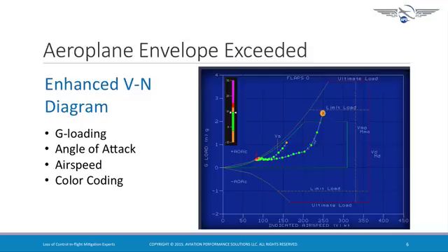So the goal in this particular case is for the airplane to ideally stay within the envelope where all the factors are going to be green. Okay, in this particular case, we can see as the airplane unloads, as he gets slow enough, though, his unload isn't quite sufficient for the airspeed encountered to avoid the stall, which is what the red indications are here. The airplane just lightly touches the stall, and the length of the little line actually shows how much the exceedance of the critical angle of attack occurred in that particular plot.